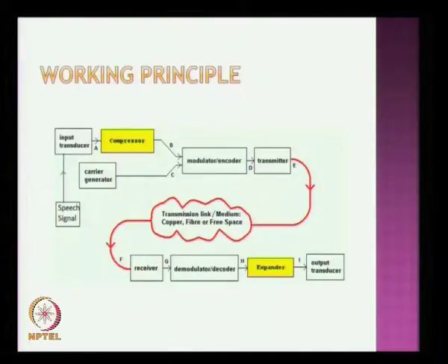Now, this is the flow process of a completely separated PA system where the receiver and transmitter are completely different. The speech signal is given to the input transducer, which is compressed along with the carrier wave and sent to the modulator and then transmitted with the help of an antenna, which is received by the receiver, demodulated and sent to the output transducer, mainly a speaker.